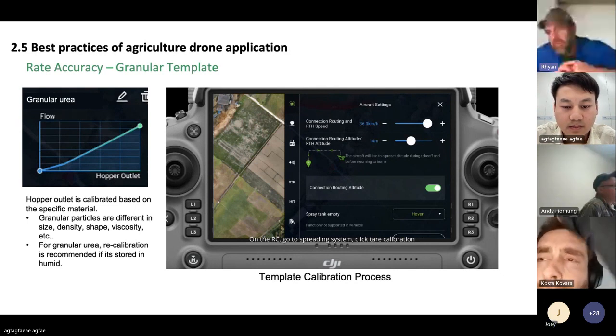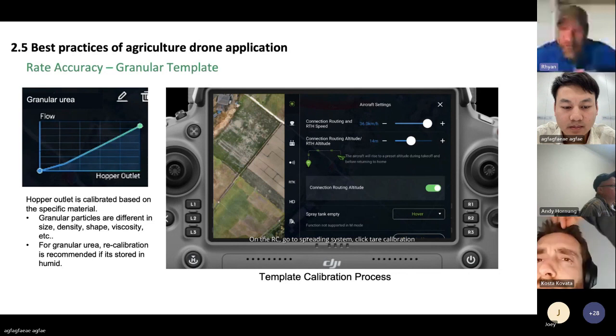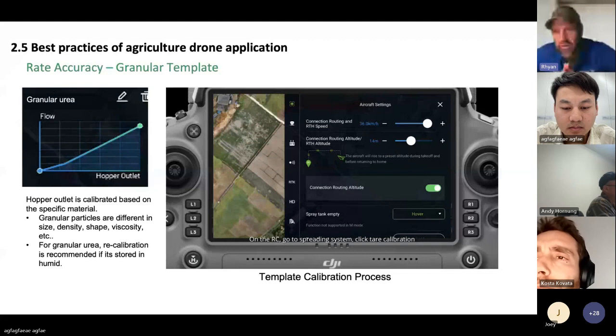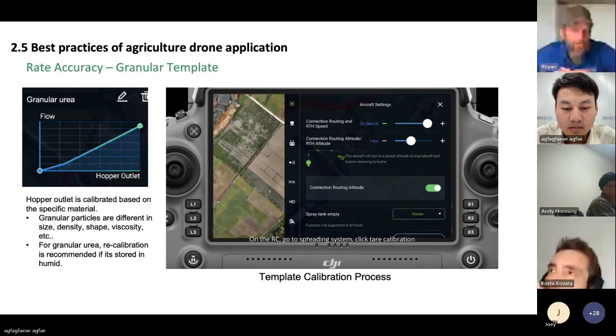If you're just running, say, 12 pounds of clover to the acre, and you're using that big gate that comes in it, it's very difficult to control that flow rate and get the spread you're looking for if you have that big gate in there and you're looking at low rate stuff. Put that other gate in there, and it's much better control at your fingertips.